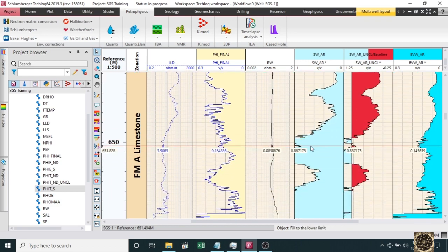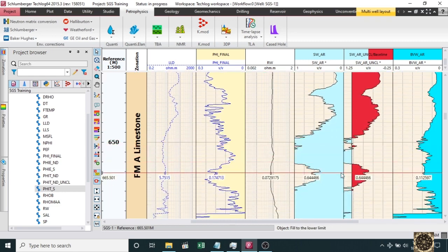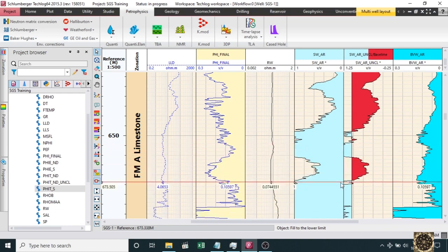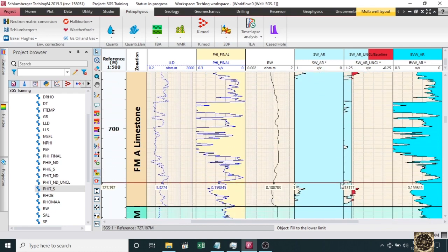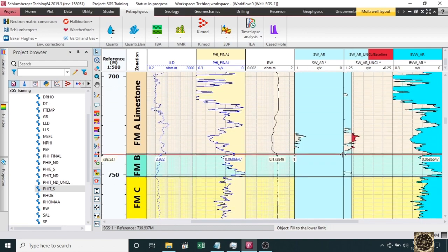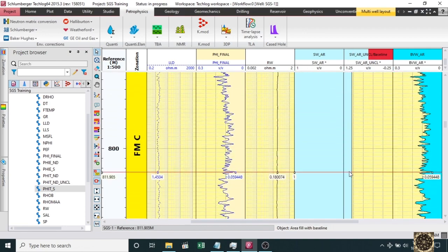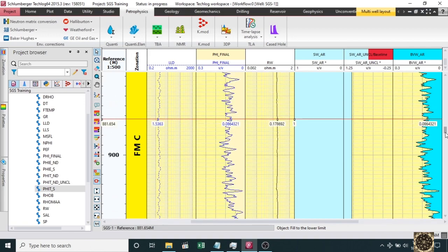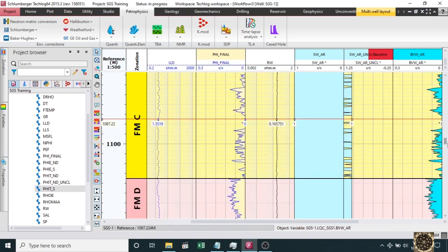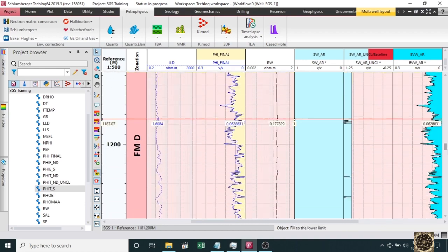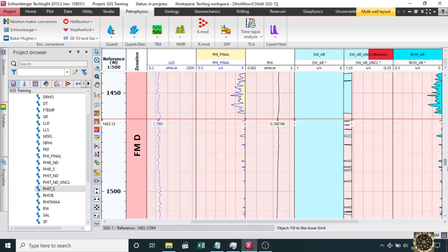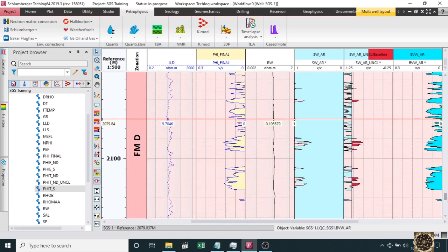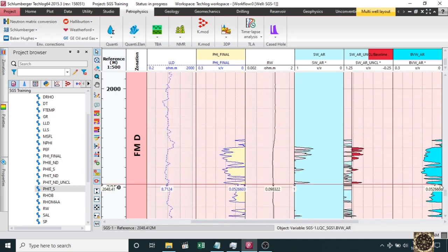Let's move down. There is a high water saturation. Again, this is 60 plus. This is 100% water. Again, move down. This is 100% water down there. Now again, it's all water. We have another zone in the lower portion where we have good porosity that we have checked in the neutron density, where we found the crossover. So let's check those zones. So here are those zones.